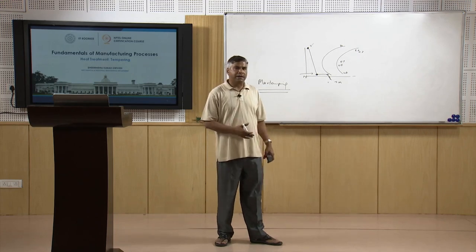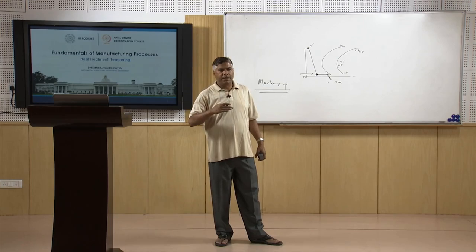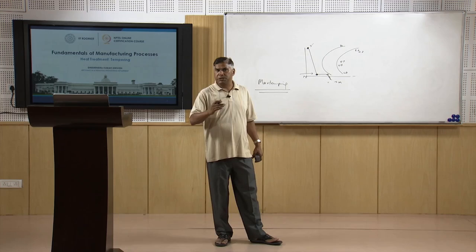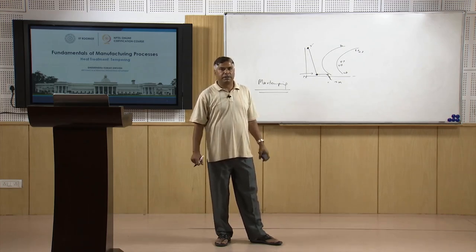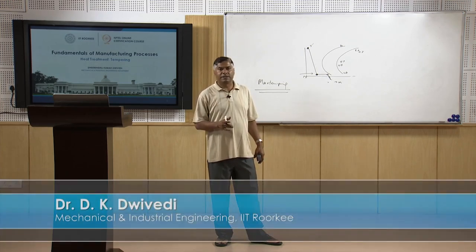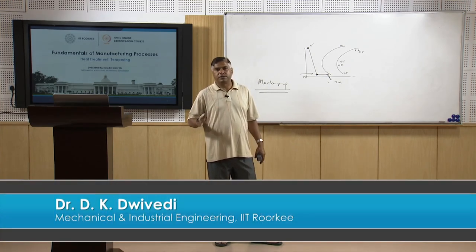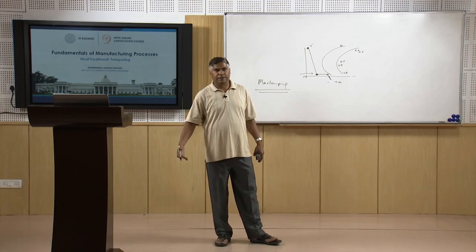While in case of the Marr tempering, we use the two-stage quenching where austenite is first quenched in the bath kept at above the MS temperature, and then quenched in another bath kept below the MF temperature. So this kind of treatment helps to reduce the residual stresses, reduce the distortion tendency, while improving the mechanical properties in terms of hardness, toughness and ductility.